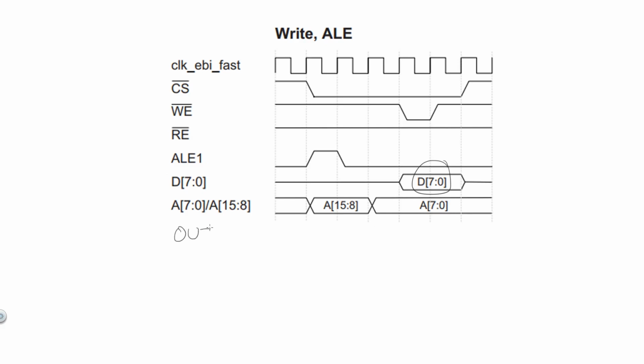So I'm going to make a new signal here and call it out control, because it's going to be the control signal to our output port. And remember, I want a rising edge when the data that we want to go to the output port is on the data bus. So that happens to be in this region right here. If you make an observation, when the write enable signal goes high, that's more or less exactly where we want our out control to also have a rising edge. So I'm going to model my out control signal off of the write enable signal.